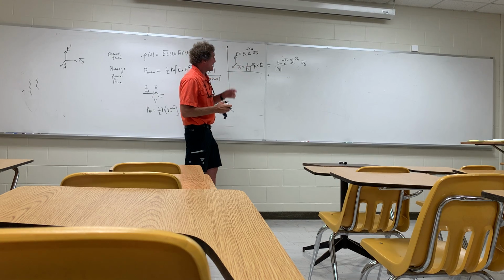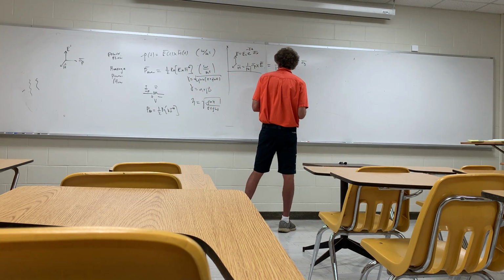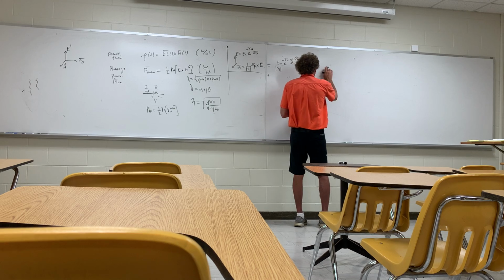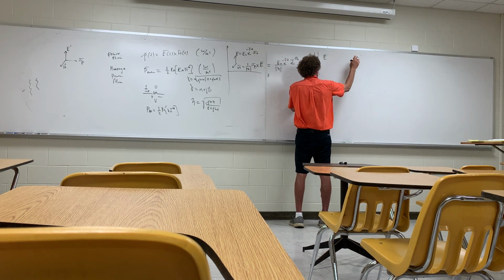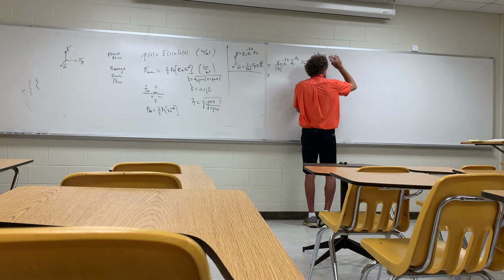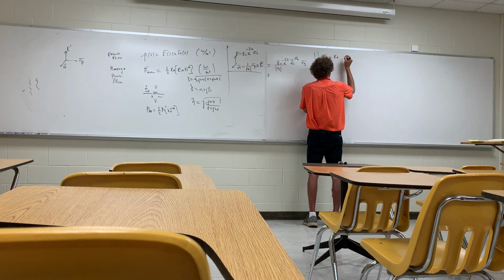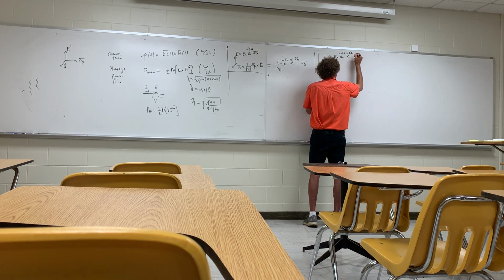Now I'm going to expand this a little for both of them. That means if I take a look at the actual E field and H field, the E field itself, for this simple waveform, we'll have some magnitude E naught. This is going to be a wave propagating in the positive z direction: e to the minus alpha z, e to the minus j beta z, as such, in the a_x direction.